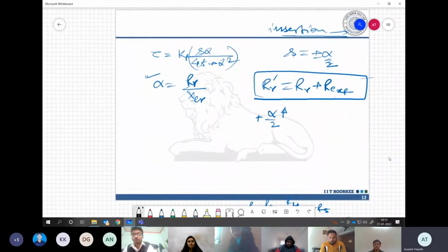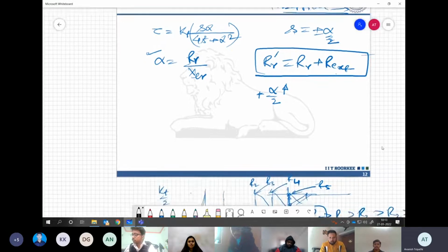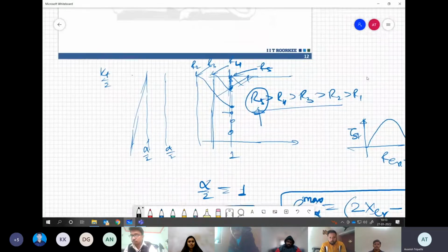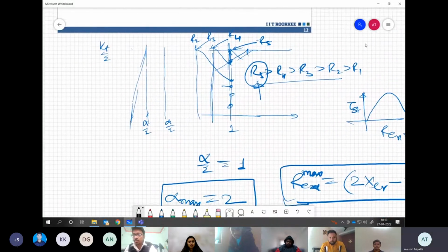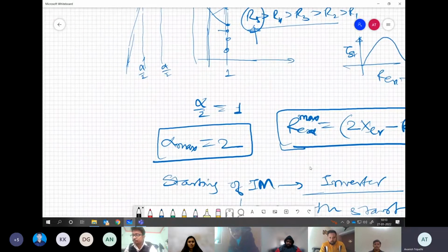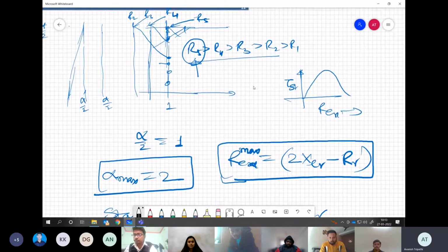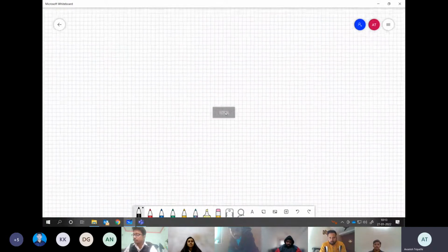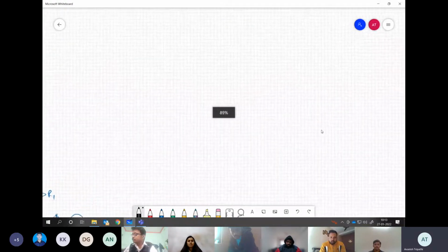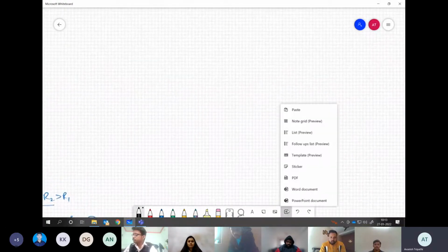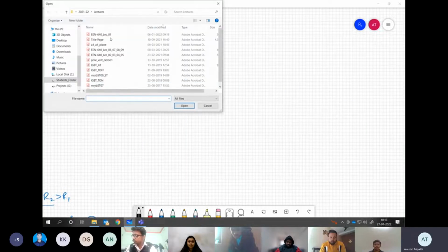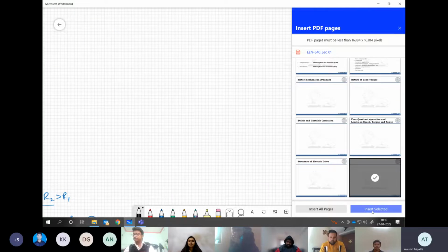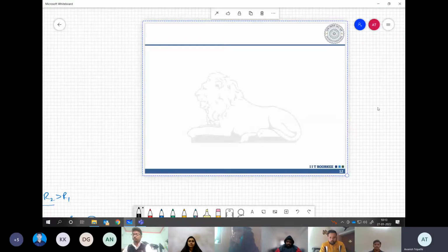Okay, now we are going towards the rotor resistance insertion. Some of the things are deleted, I don't know why. I will draw it again. So we have seen the effect of inserting some resistance within the rotor circuit, particularly for wound rotor motor, we are finding this useful. If we want to improve the starting torque, a little bit more detail we will see today regarding that and other ways we use to start the induction motor.